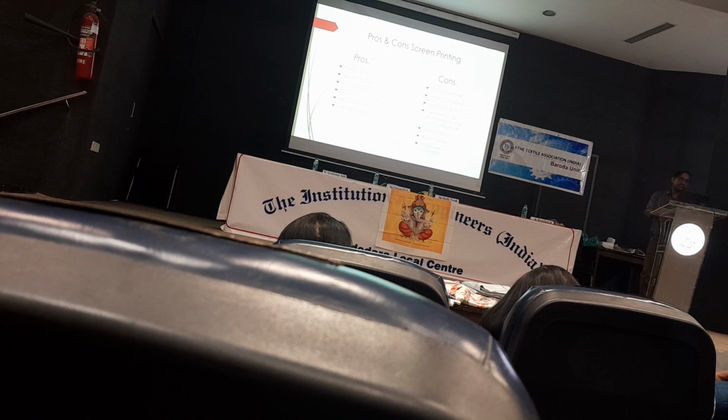Expensive in short run. Why is it expensive in short runs? I think this is the main question. Whenever we start with screen printing, the rotary screen is made from a particular metal, and every time after use of the design, the fashion will change. So the screen we prepared for the design becomes useless, and that screen definitely goes to the garbage. So every time the screen cost has to be considered, and the screen cost in today's scenario